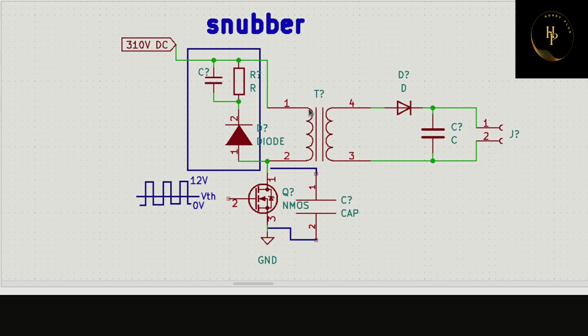Because here is an inductor and here is a capacitor. That is not physically connected in this circuit. That is a virtual capacitance of this MOSFET, source to drain. That is your source point, that is your drain point. So this is the source to drain capacitor. This coil and this capacitor automatically resonate and make this ringing.